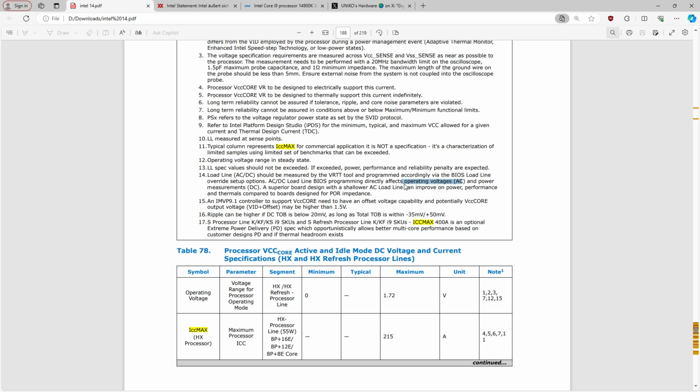Basically, ASUS takes the VID table, does some math with it, and converts it into a number that indicates rough silicon quality. But the problem is each CPU gets its own VID table from the factory, and how much headroom there is below the VID table for the CPU to maintain operation actually varies by CPU. So you can get some CPUs with really good VID tables with no undervolting headroom, and you can get some CPUs with very bad VID tables with tons of undervolting headroom. And you can also get CPUs with very bad VID tables and no undervolting headroom.